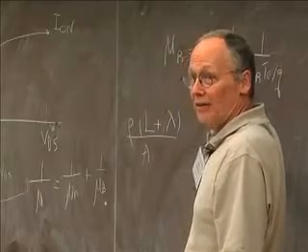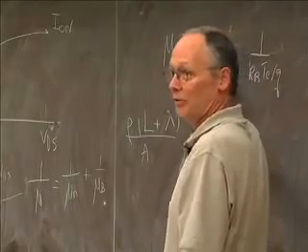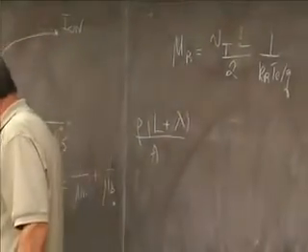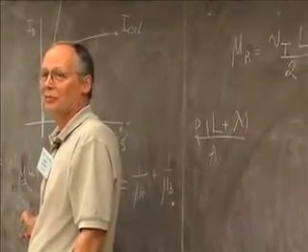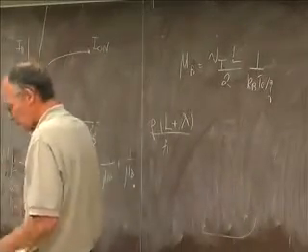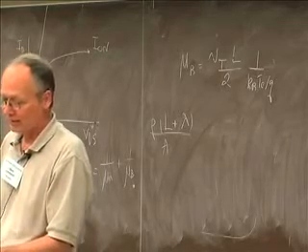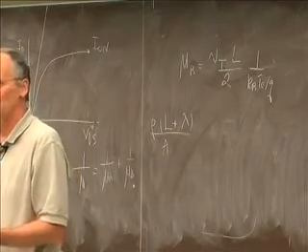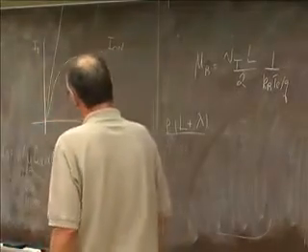So as you scale and get transistors denser and denser, this ballistic mobility gets smaller and smaller, and it tends to dominate. So you get some boost, but you don't get nearly the boost that you would expect just by looking at the differences in the bulk mobilities. Okay. But there is this advantage alluded to in the second question. Is it that we can get the same current levels at longer channel lengths? Yes. So with relaxed geometry, especially if you're looking at RF devices, you can get very high performance.